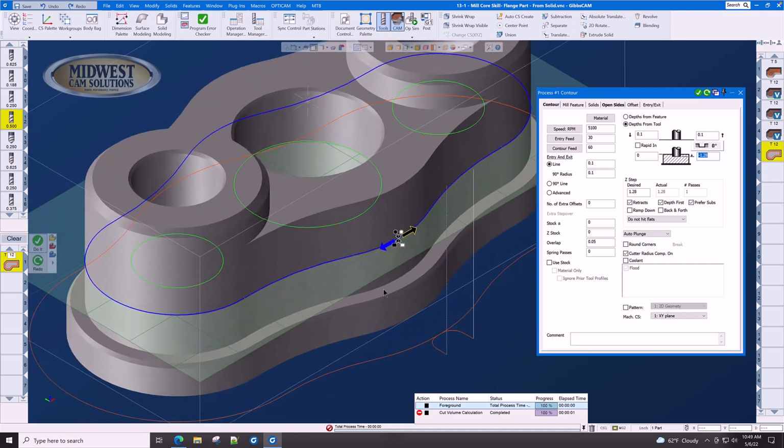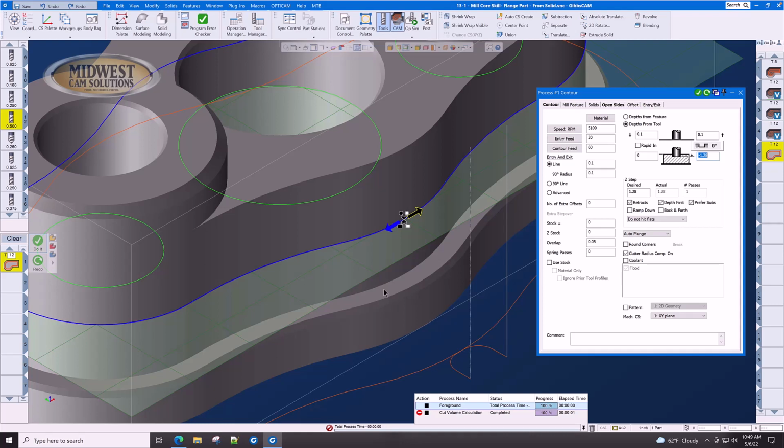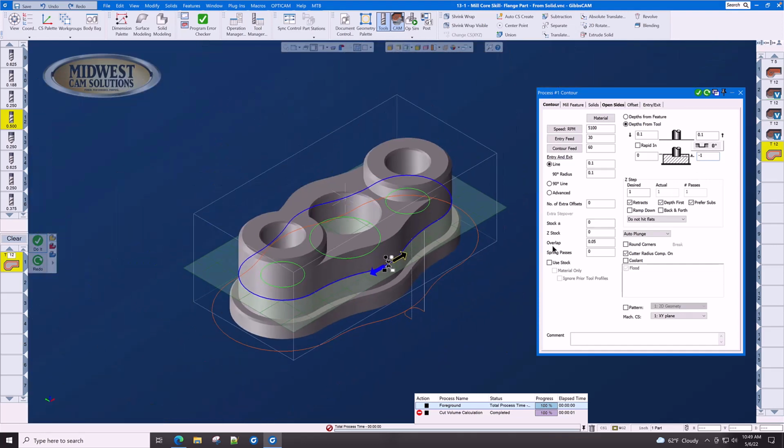Can we get those dimensions directly off of the solid? Yes. Double click here in the bottom Z of the toolpath field, press your Alt key, and you can see that your interrogator cursor is now up. Click on the surface, and that surface has been added here into the bottom of this toolpath Z.